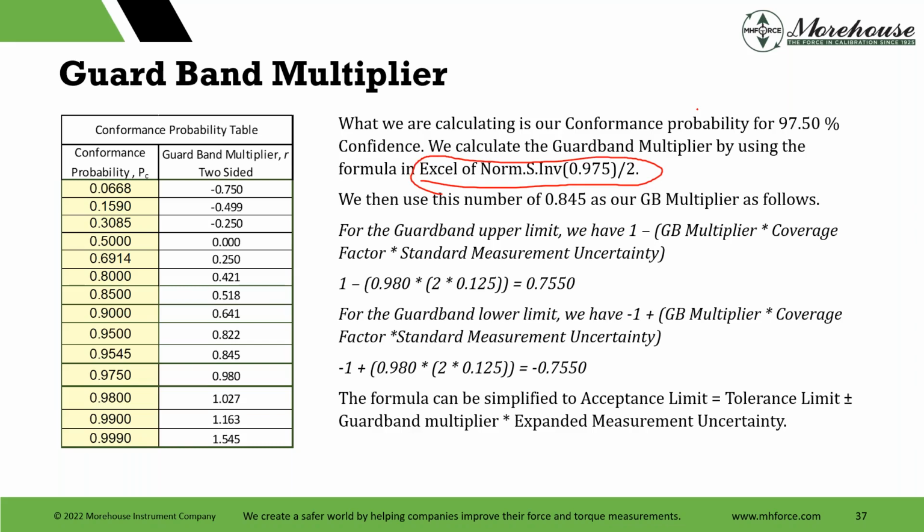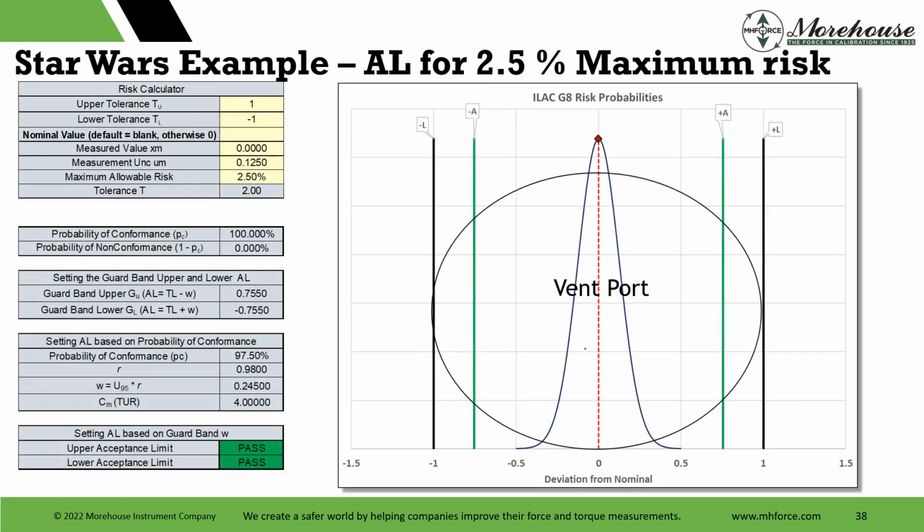When we use this number, we can calculate our upper and lower acceptance limit for this, and we're basically saying with 95.45% measurement uncertainty, allowing for that 4.555% risk, that we need to take a shot between the plus or minus 1, and that shot needs to go in between these 2 numbers, and these 2 numbers represented here by this graph.